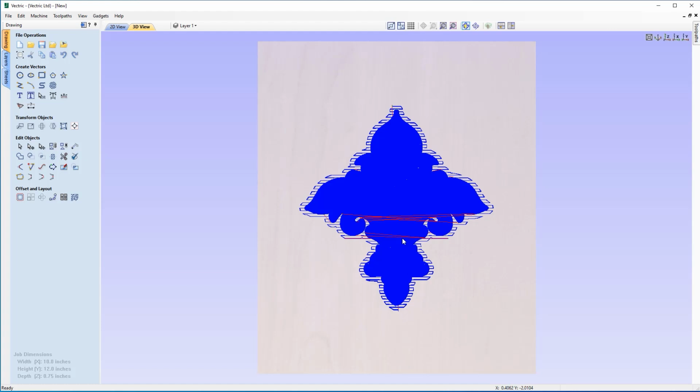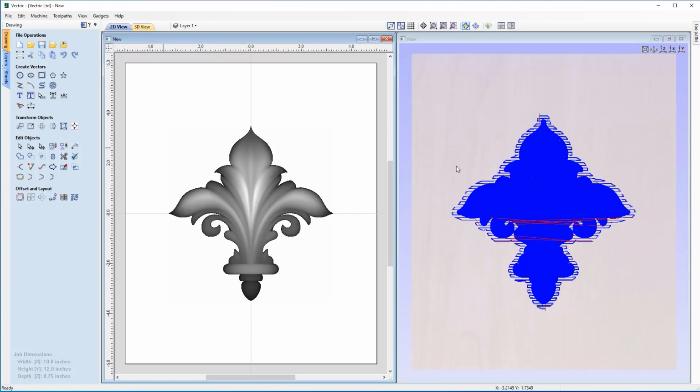And there we are. You'll notice that this is actually showing the toolpaths. If I just tile my views by clicking this button up here to vertically tile them, you'll notice on the left-hand side, we have the bitmap representation of the model we have. And this blue representation here is actually just the toolpath. So on the 3D view here, this isn't an actual bitmap. This is just a representation of the toolpaths that we saved earlier in Design and Make Machinist.